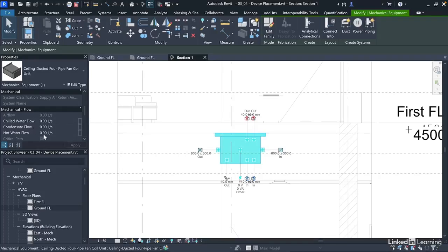But then you can notice that on the water side, this is actually the child component. The plant is the parent to this. So that is why I'll have to preset. When we get to that stage, we preset the water flow for all the various water systems. At this point, you will want to repeat this workflow for the other 10 zones to place the air terminal and zone equipment.